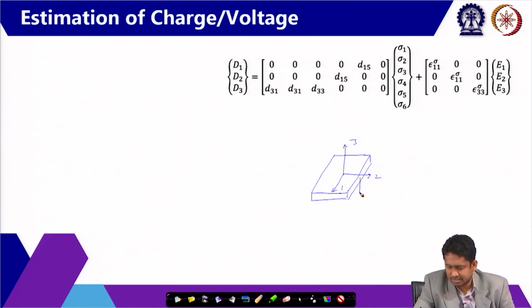So, the shear is sigma 4 is equal to tau Zx, or we can call it tau 31 as per our nomenclature 1 2 3 of the axis, and then we have sigma 4, and we are measuring the electric field along the axis 1. So, here these faces have to have electrodes deposited to measure it, and we are trying to measure the voltage here.